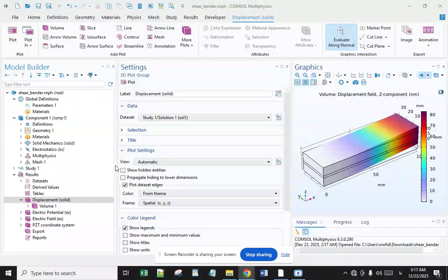It was shown that the surface-mounted actuators acting through the E31 piezoelectric constant induce boundary concentrated forces and moments in the structure, whereas sandwich shear actuators acting through the E15 piezoelectric constant induce distributed moments in the structure. Therefore, we can expect fewer problems of actuator debonding at its extremities for the shear actuation mechanism.